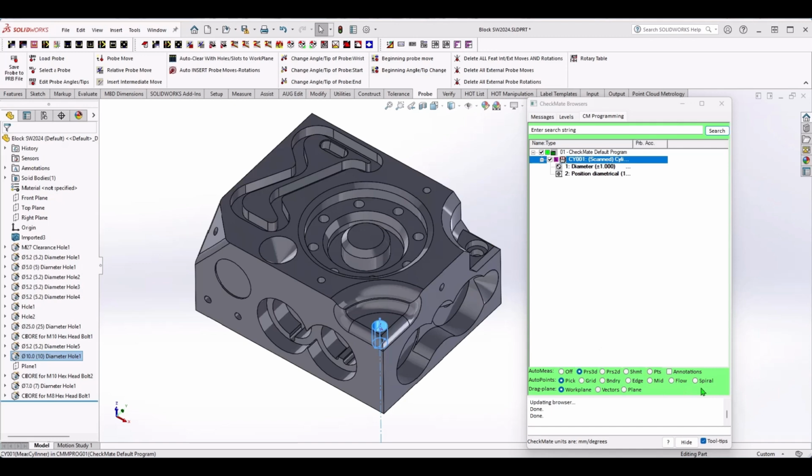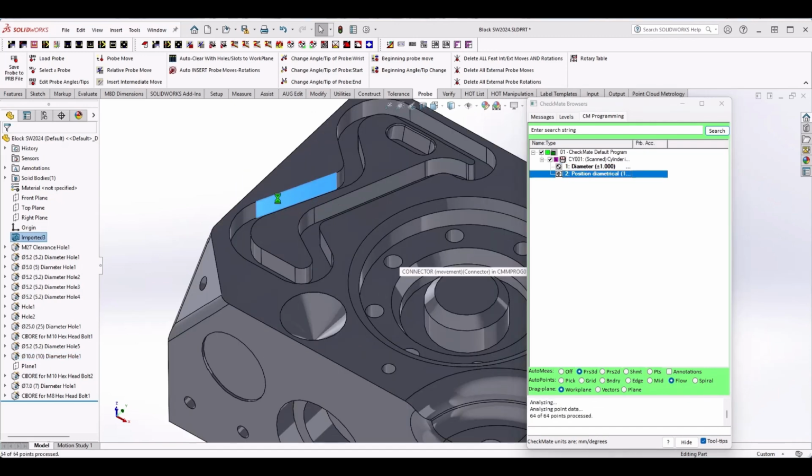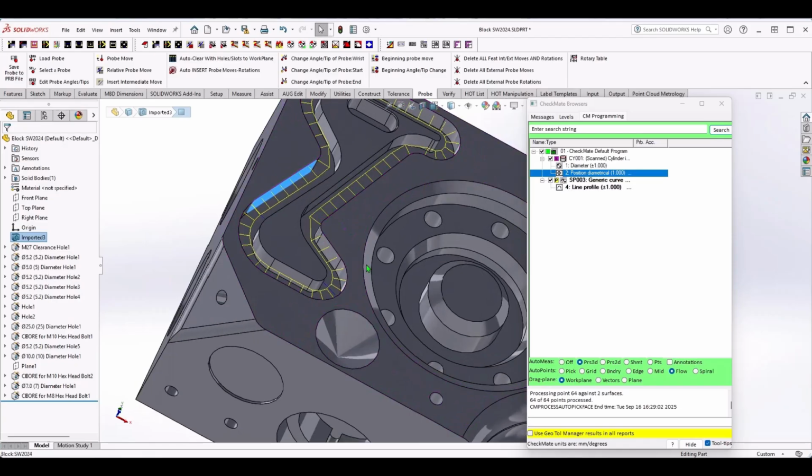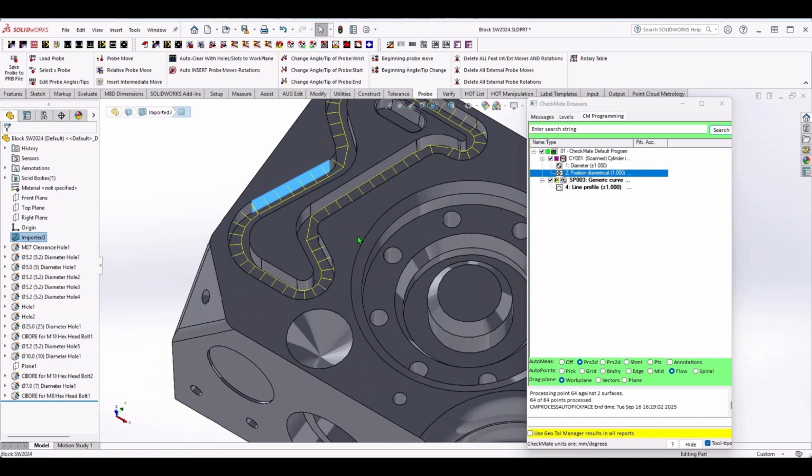By creating a surface measurement, I'm going to do the face, so it measured a trim. Okay, that point spacing. Now, when you see this point spacing and you're saying, oh, it's cutting the curve, keep in mind, when this is run on the CMM, there's material there. It'll typically find its way around the curve. It won't tell the CMM to drive straight between there and there. But yes, you may want to have more points.